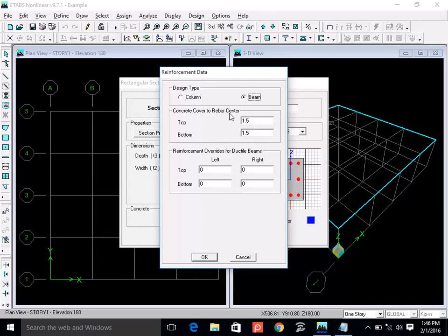No matter what units designers use for their real design, the bar sizes are used in FPS units. Sometimes drawings are prepared in SI units, millimeters and meters, but the bar sizes are still the FPS bar sizes. So you need to be familiar with these sizes. I will show you a table. You may have it in your concrete book by Dr. Zaidul Siddiqui, a table at the end which shows all the bar sizes.